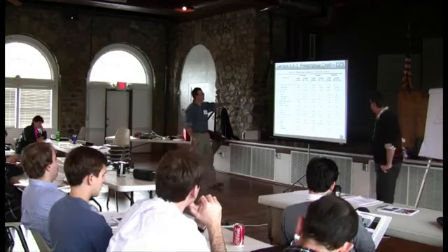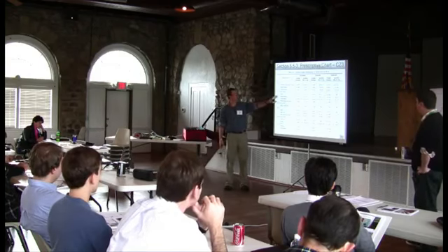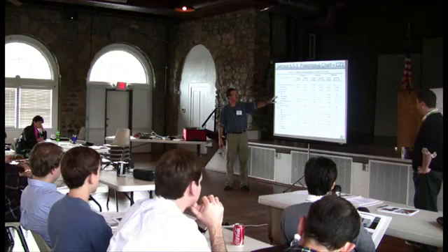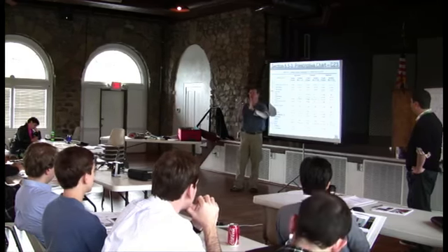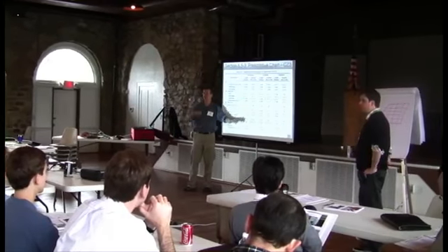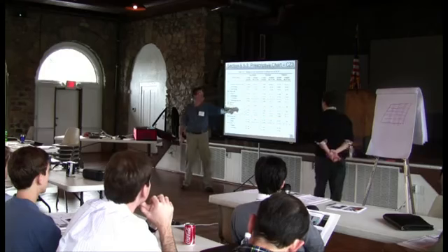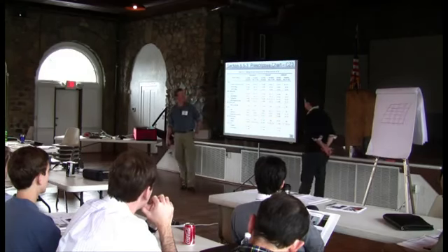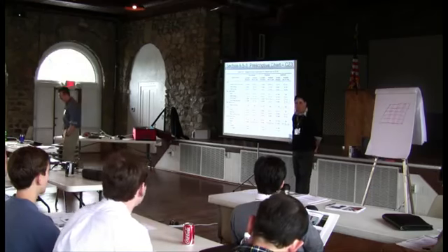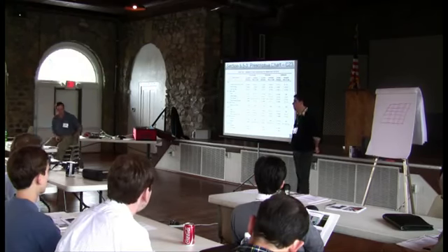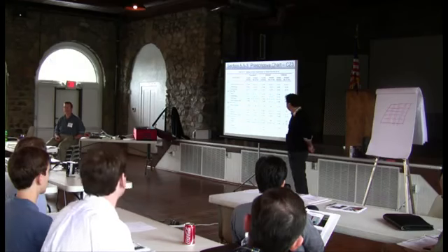All right, Brandon, we've got walls, and it's listing four types of walls, and metal buildings is just a straight up R13. So that's about 3 inches of that fiberglass, or 3.5 inches, I guess. You should have documentation that should tell you that's an R13. Mass walls? Mass walls are, if you've got block, concrete, brick, what have you, they're asking for you to put an R7.6, essentially an R8, continuous insulation.